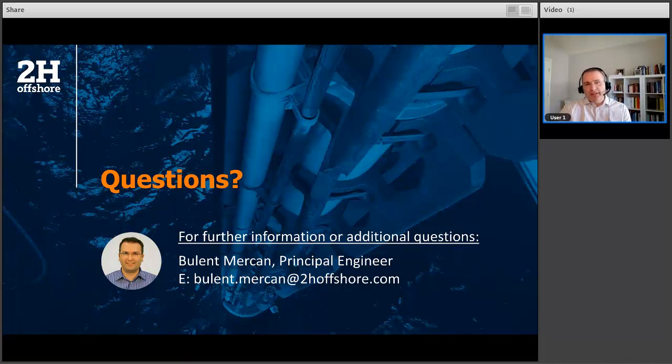But in this case, it is done in the frequency domain, and like I said, we used Dirlik's method for these fatigue calculations. There are also other methods. Rainflow counting can be done. Again, you are using a transfer function approach, but you do rainflow counting to do the fatigue calculations.